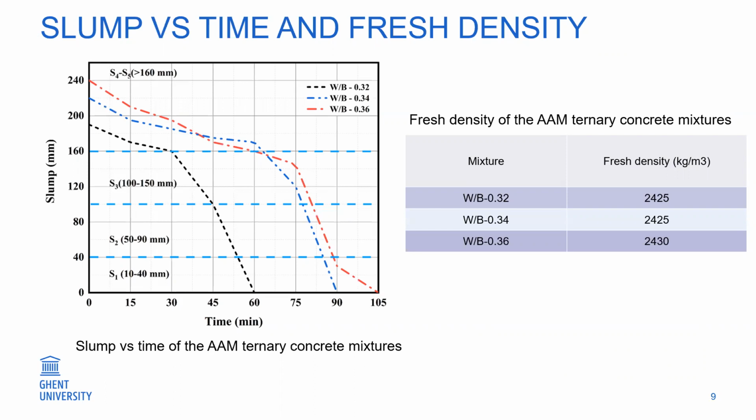As can be seen in the right table, the AAM mixtures displayed the same fresh density, indicating that the water to binder ratio did not affect the fresh density of the alkali activated ternary concrete mixtures.